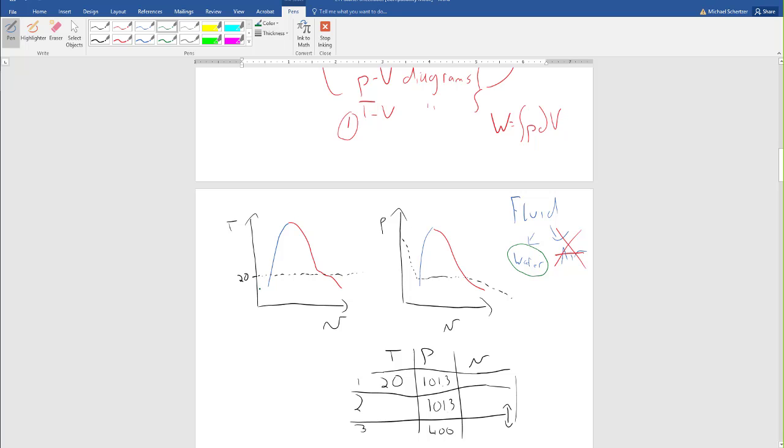So here, if I wanted to draw a constant pressure line, this is P equal to 1 atmosphere, and this would line up with 100 degrees over here. So my state 1 is over here. State 1 is a subcooled liquid, so we know that for sure.